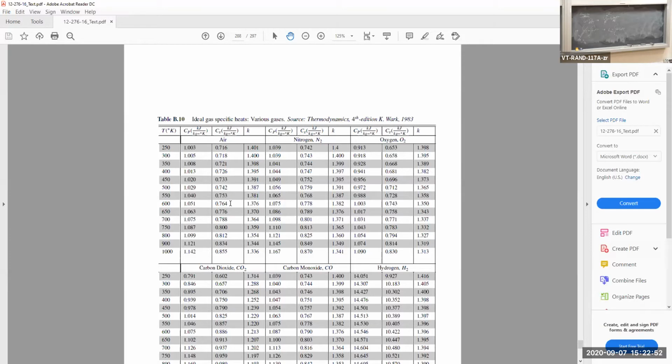So the specific heat over our process, as the system heats up from 300 to 600, is changing a little bit. It's increasing by about 10%. So CV is not entirely constant during the heating process. It's getting bigger as temperature goes up. So what are we going to do?